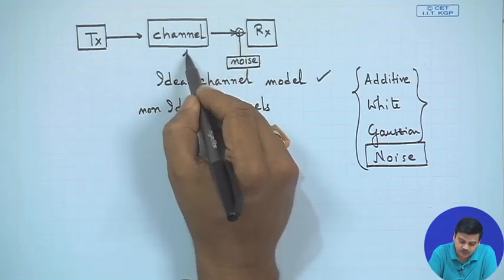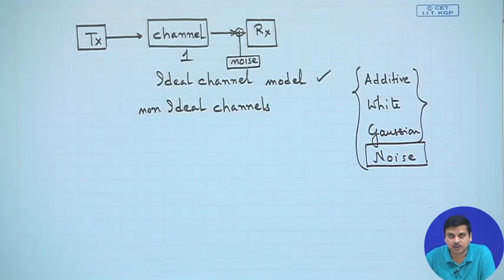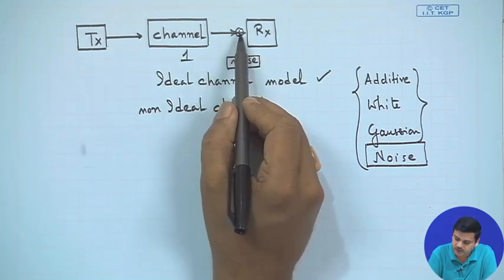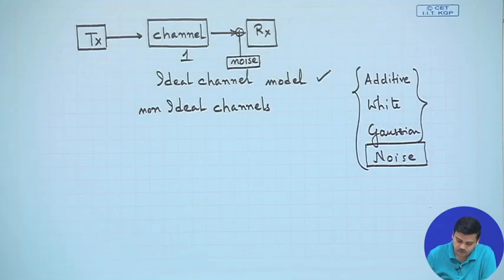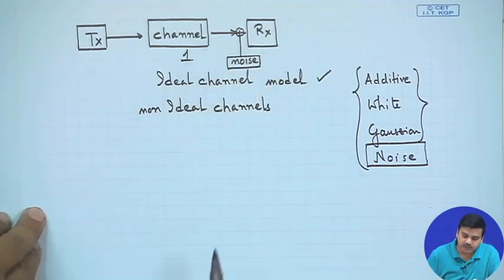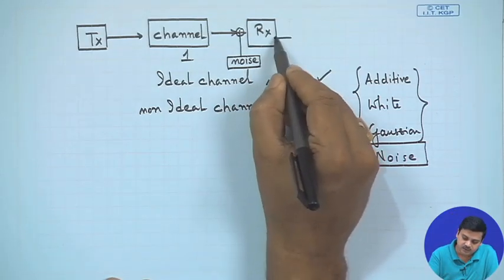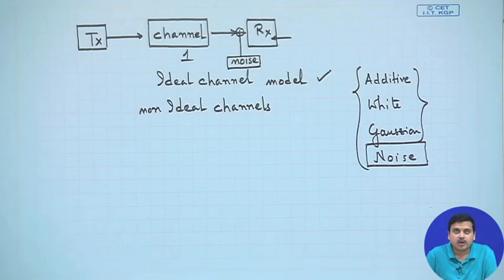is such whose gain is 1. That means, the signal is left undistorted, only there is addition of noise in the receiver. So, for this kind of situation, which is quite idealistic, we would like to design a receiver under that condition. So, one would question what is the point of discussing such a system where the channel is non-distorting, there is no effect of the channel and there is only noise.